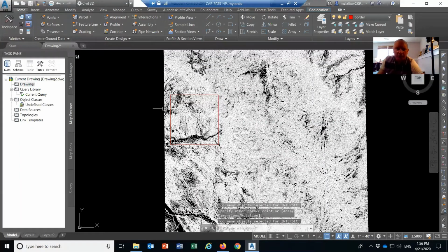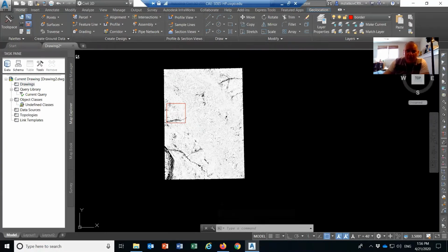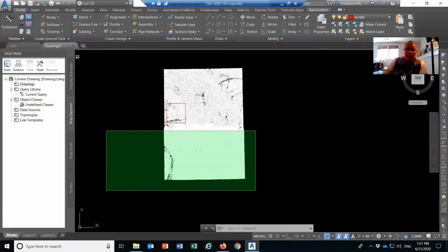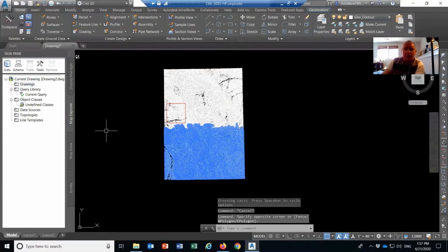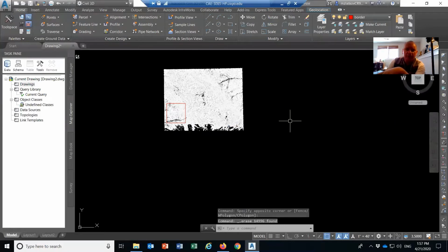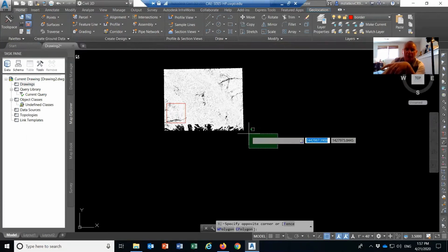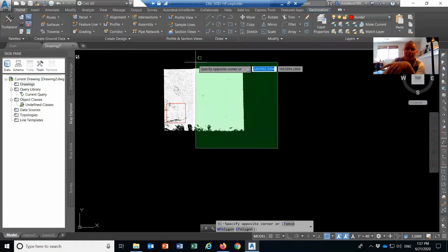Now, the other thing I can do, since I have a bunch of elements that I really don't need, is get rid of a lot of them. I can delete a lot of these elements that I'm not going to use. I just want to make sure that I don't delete anything that goes inside this rectangle. If the properties tab, the toolbox I showed before, is turned on, this is going to go so much slower. So make sure this one is turned off, and then you can easily work.